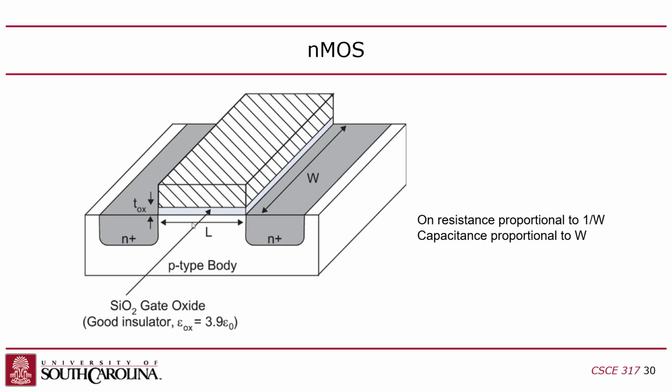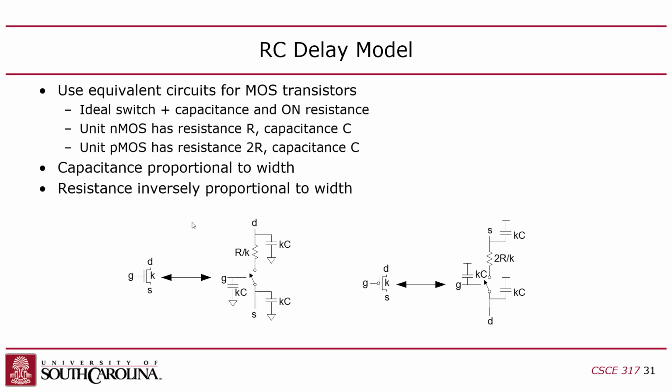You get twice the capacitance on the gate, which is the input of your logic gate, right? And you get twice the capacitance in the diffusion areas, which is the output of the logic gate. So you get burned twice for that extra power, that lower resistance. The resistance is the drive strength. You lower the resistance, you increase your drive strength, but you add more capacitance internally.